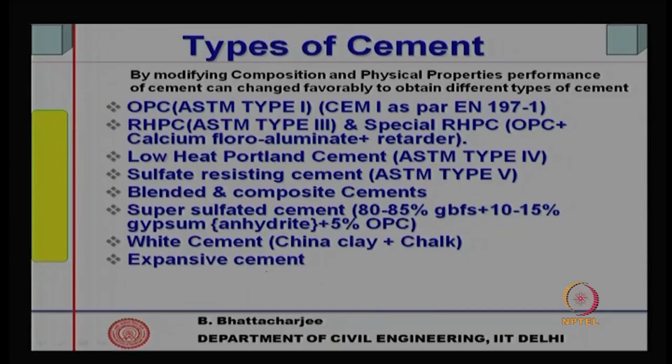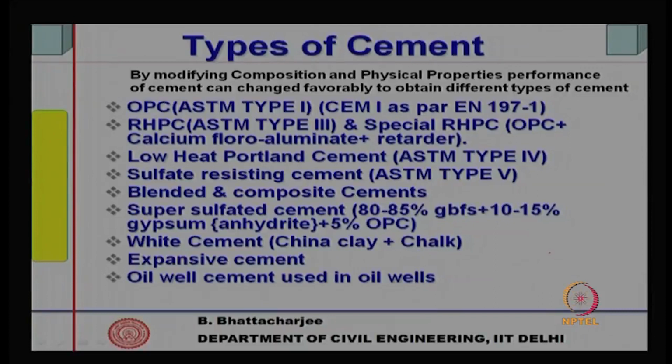Expansive cement is used for filling in grout holes or as shrinkage compensating cement. So, you want to fill in cracks or similar situation. Oil well cement is used in oil wells, petroleum, crude oil wells. Actually, they have special setting characteristics, specific, stringent setting characteristics, and of course, they should be sulphate resistant. So, we will look into some of this in details, and maybe we will come back again to this slide